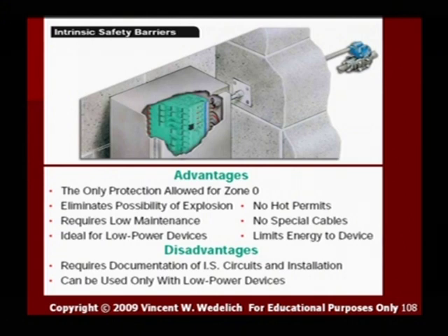low power devices. You don't require a hot permit. No special cables, and you can actually install regular general purpose conduit installation, no seals or anything going into the hazardous area because you have limited the energy. So that's an advantage. It limits energy to the device.